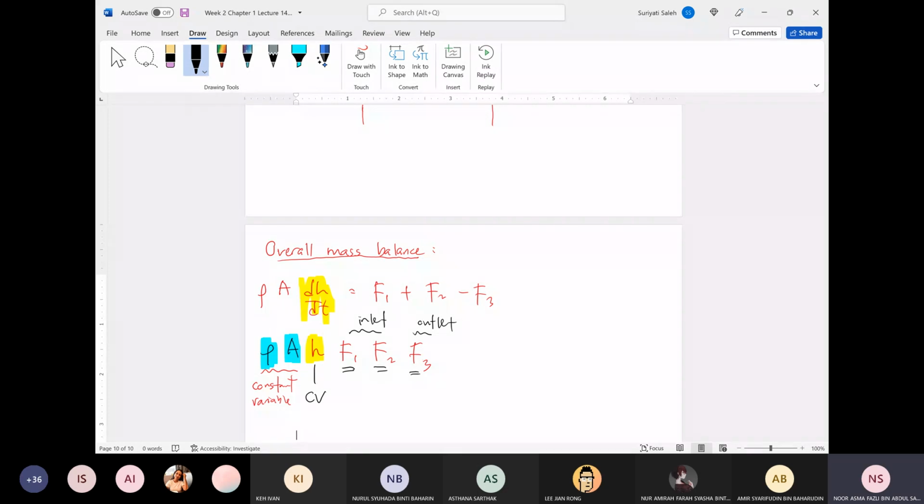So it's better to observe how the inlet influences your level before you adjust the exit flow rate. It's much easier compared to selecting the inlet as your manipulated variable. That is the explanation why the exit flow rate is most suitable to be used as your manipulated variable.